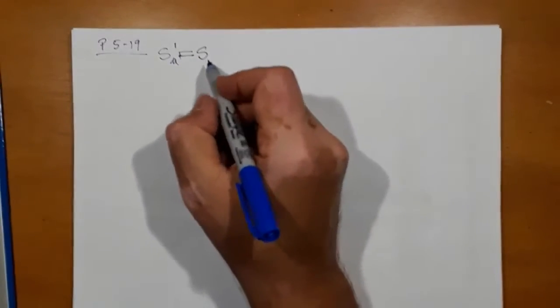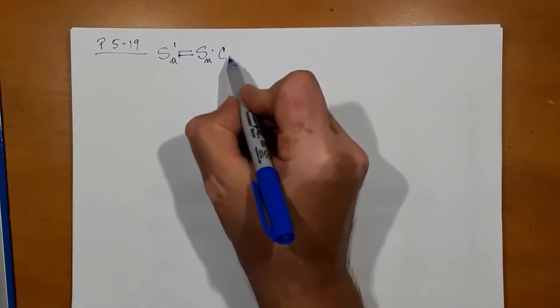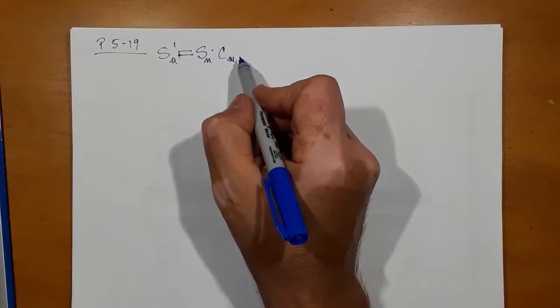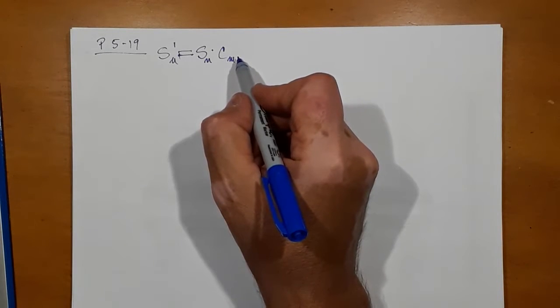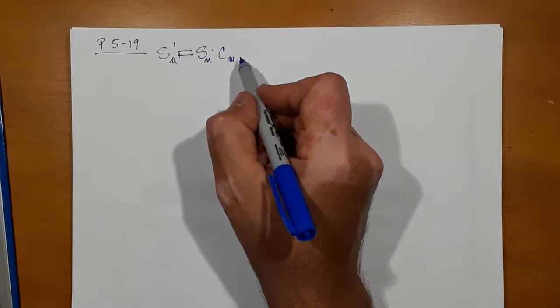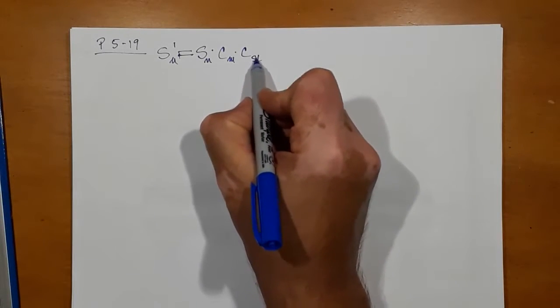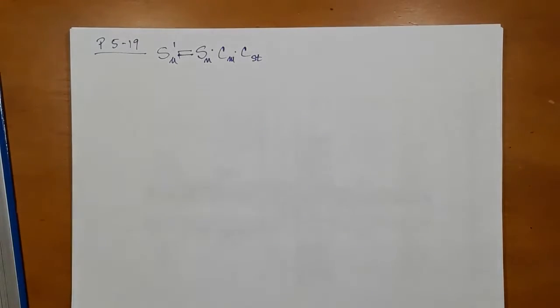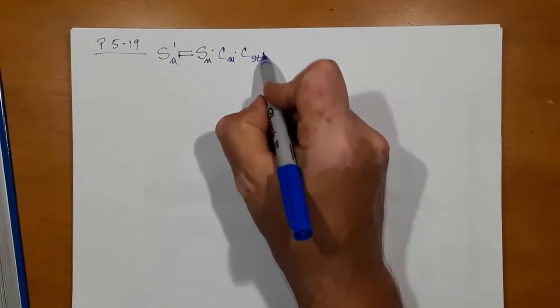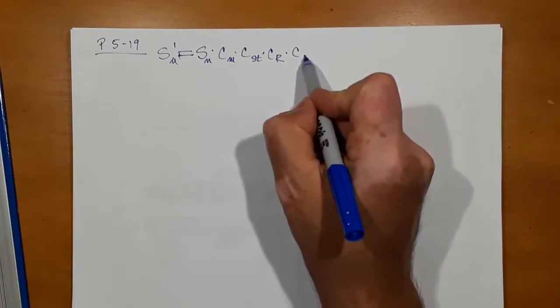And the entire equation is Sn times these coefficients, the material factor, the type of stress factor, the reliability factor we need to discuss, and the size factor.